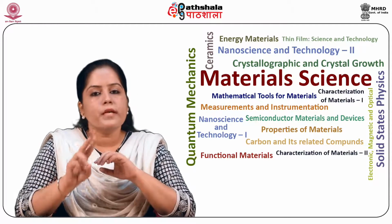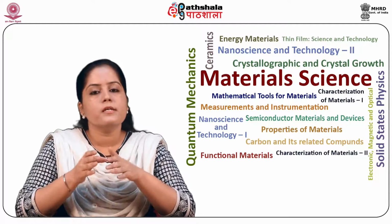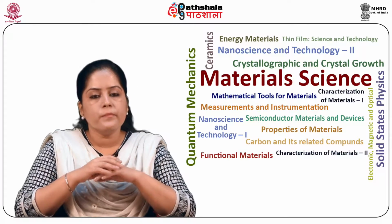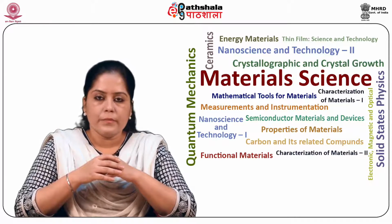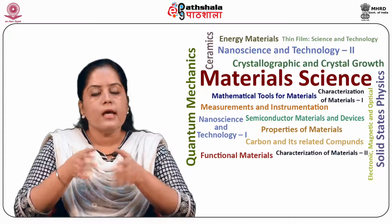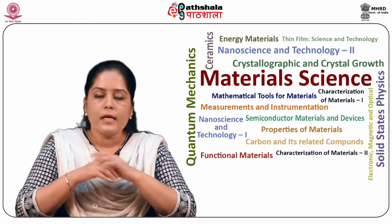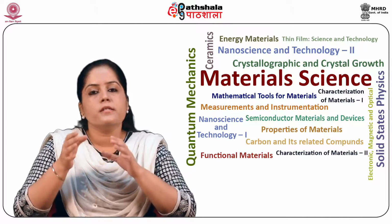There are two main structures that are generally used. That is, first is the self-aligned ion implanted structure and the other is the recess gate structure. The electrodes, mainly gate, drain and source, are made up of metallic contacts in the self-aligned ion implanted structure.